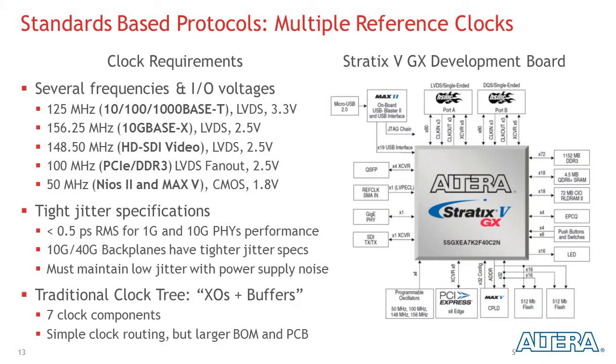I think this slide is a good way to introduce Min and the Altera solution, but I wanted to highlight that on the left, it shows all the different timing requirements. Design engineers today are seeing these in their typical designs. It shows possibly a PCIe switch or several Ethernet standards, whether it's 10 gig or gig PHYs that are in the design. These devices all require different clock frequencies, anywhere from 100 to 156.25 megahertz.